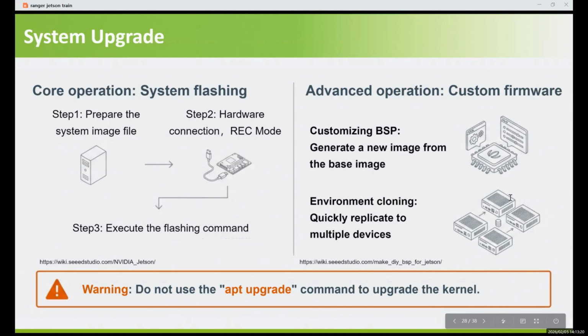The system flashing process is also fairly straightforward. First, prepare the system image file. Second, set the device to recovery mode. And third, execute the flashing command. For the detailed process, please refer to the wiki pages of respective products listed here.